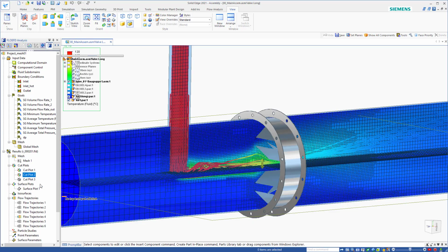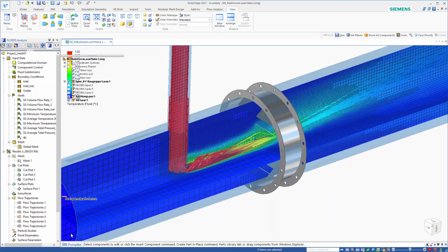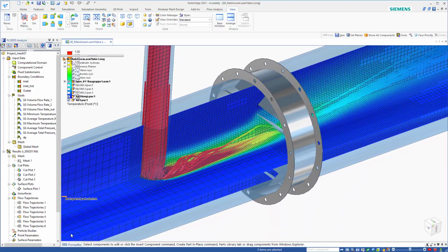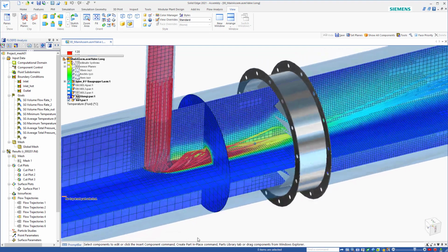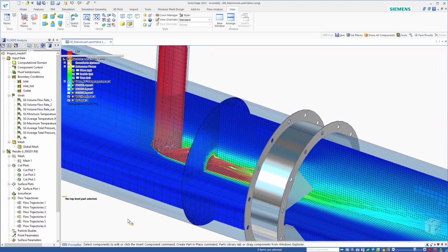Different cut plots show several regions of the results and the refinement. The visualized parameter is temperature. The hot gas is shown red, and we can clearly see the mixing behavior in the larger duct, behind the protruding small pipe and in the damper area.